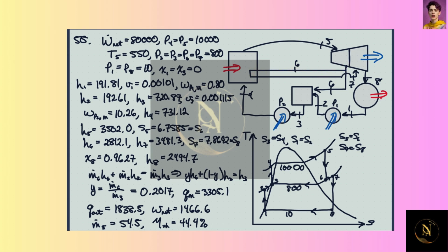And then we have it coming back and being fed into the low pressure turbine. There's some steam at this pressure to feed the feed water. The rest of the steam is reheated and is expanded in the low pressure turbine. So we take it all out of here, reheat some of it, and then use some of it here, and then feed it back into this.